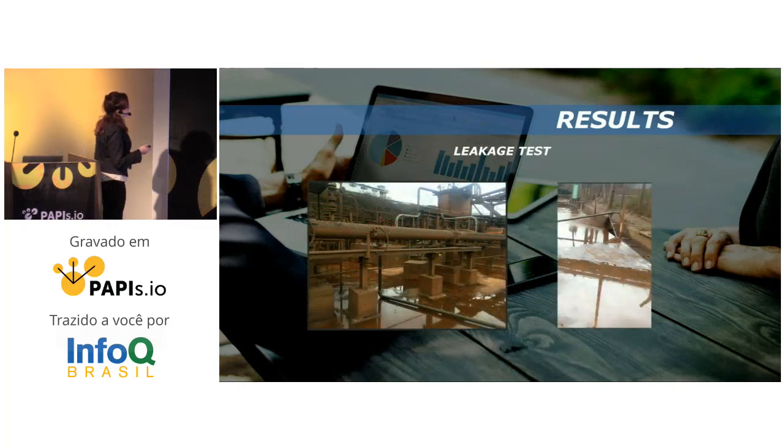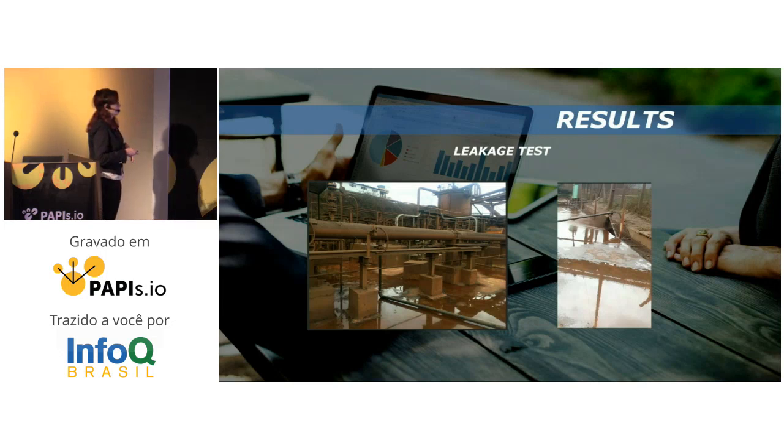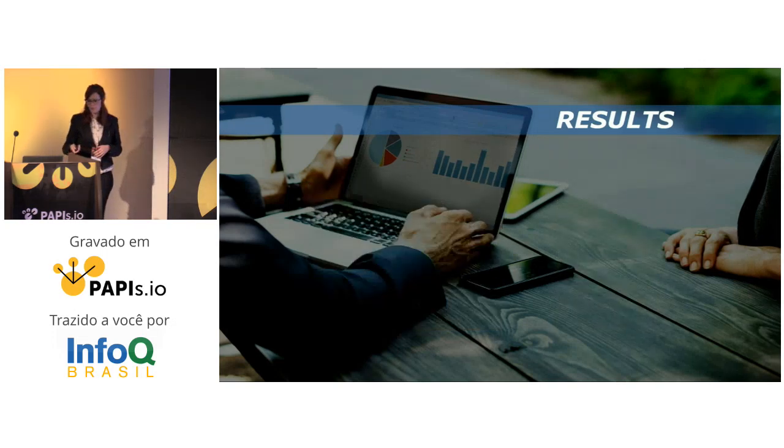So here, as you can see, this is the pipeline, and I don't know if you can see, but there is a drain here between 2 points of pressure measurement. And basically, what was the leakage simulation? We opened this drain, so the slurry flow was deviated to a hole in the ground. And this deviation of the slurry represented a leakage on the pipeline. So we ran this and looked at the process variable to see what the system response was.